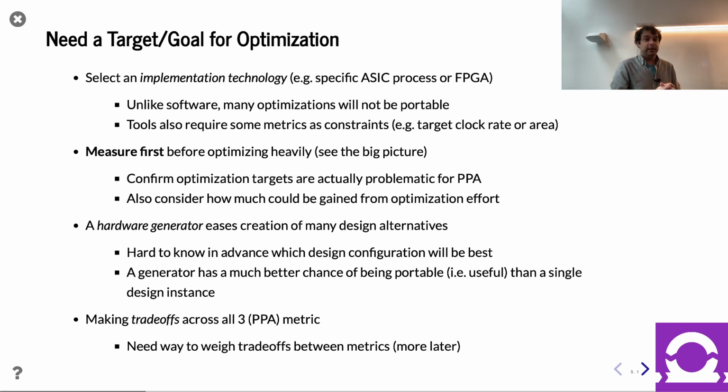And so, for the last 10 plus years, when you're building optimized hardware for AI, a lot of time is spent thinking about just how many bits of precision you need for your numbers and the format. You can have fixed point or floating point. And even amongst floating point, historically it was always this IEEE 754 standard, the common thing you always used. But nowadays for AI, they found that the choices made for the IEEE standard weren't quite what AI wants, so they would prefer a different ratio of exponent to mantissa, different dynamic range, and that sort of stuff. And so there are all sorts of other numeric formats arising. In the case of the TPU, I might get this wrong, so put a caveat on this.